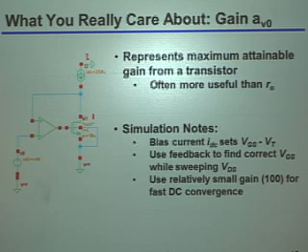Okay? Now, I'll point out that this is actually done not just to characterize it at one individual bias point. In other words, I'm not just, for example, going to diode connect that device. But what this actually allows me to do is change the drain to source voltage across that device and look at what happens to the intrinsic gain as you move that drain to source voltage around. Okay? So the way this works is as follows.